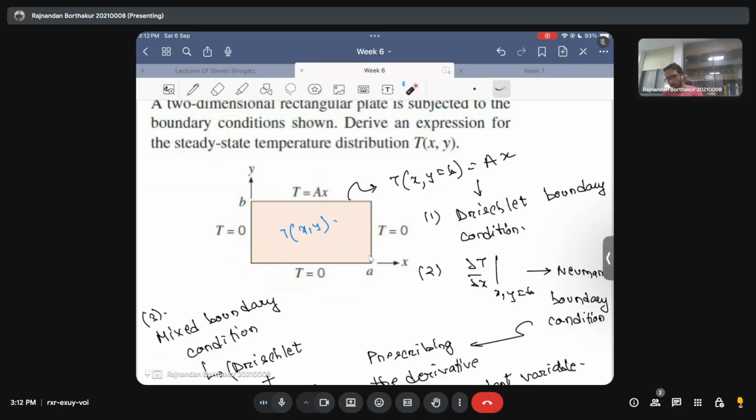You can still apply the method if, say, you have some fixed temperature, such as T equal to 5 degrees Celsius on the three faces. The boundary conditions are then not homogeneous, but you can still apply separation of variables because you can always make a change of variable. For instance, let theta equal T minus, say, T naught.